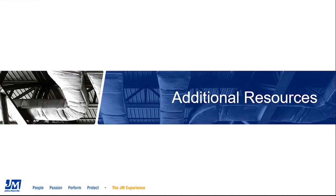All right, awesome. Our next question is, how do you adhere the Spiracoustic Plus into a metal duct? Sure. Spiracoustic Plus is self-supporting. There's no need for glue or mechanical fastening up to, I want to say, 36-inch diameter. Don't quote me on that; I'd have to go back and look at the data sheet to make sure. But once you get over a certain diameter, we recommend using pins to mechanically fasten it and hold it into place. For the smaller duct applications, the typical 12s, 14s, 16s, it's all a slip fit. It slides in, self-supports itself, pops in place and holds itself in the duct.